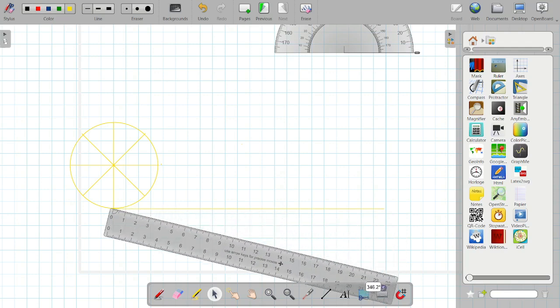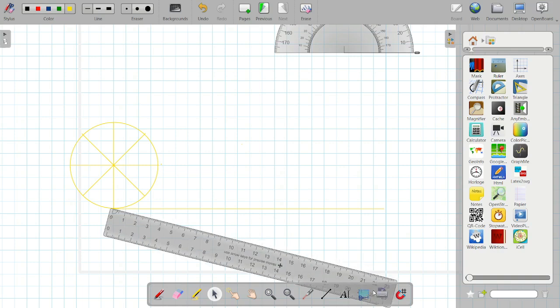So for that, I will take an angle approximately 30 degrees or so and will mark equidistant points. The distance is as per your choice. I am taking 2 centimeters. You can take 1 centimeter, 2.5, 3, anything you want. I will mark on this line 2, 4, 6, 8, 10, 12, 14, and then finally 16.